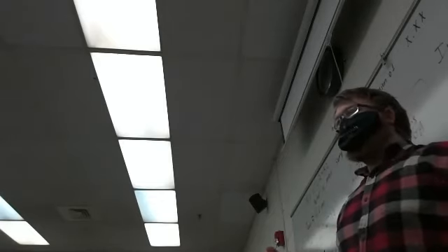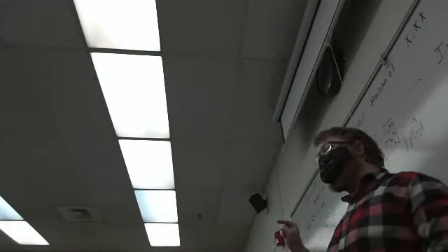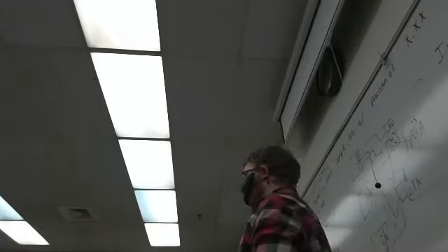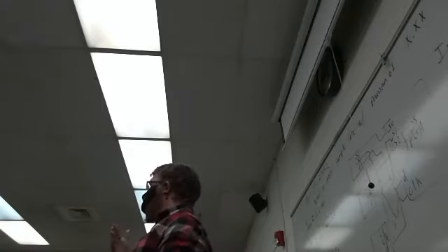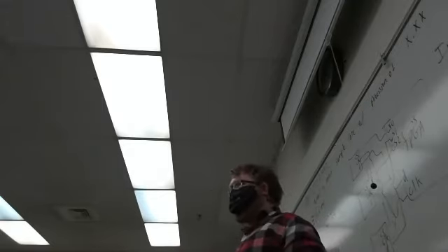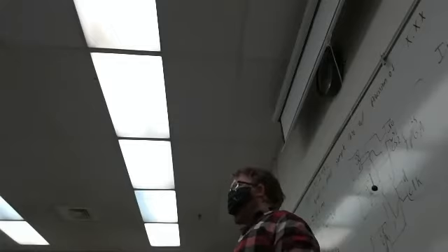Okay, so it all comes down to, we've designed a UART. The UART is the one that sends data to a computer. It's asynchronous, no clock. Well, we have to know what the clock speed is beforehand. The baud rate has to be defined. So a defined baud rate, asynchronous communication, it can start at any time, stop at any time, and the send and receive are decoupled. There is no master or slave. Then we have the SPI D to A, digital to analog converter. Then we have an I2C analog to digital converter. That's all we've really dealt with.